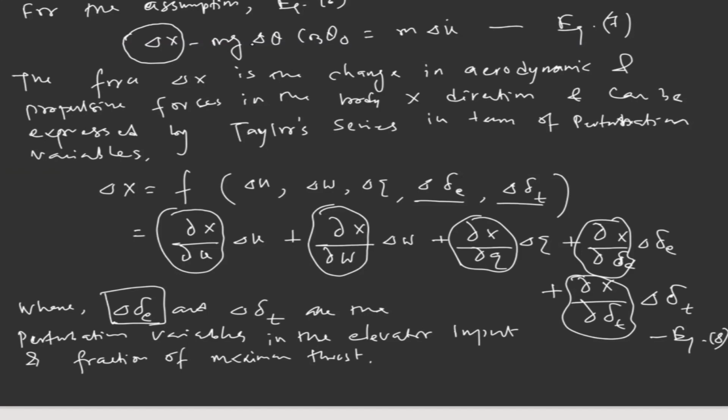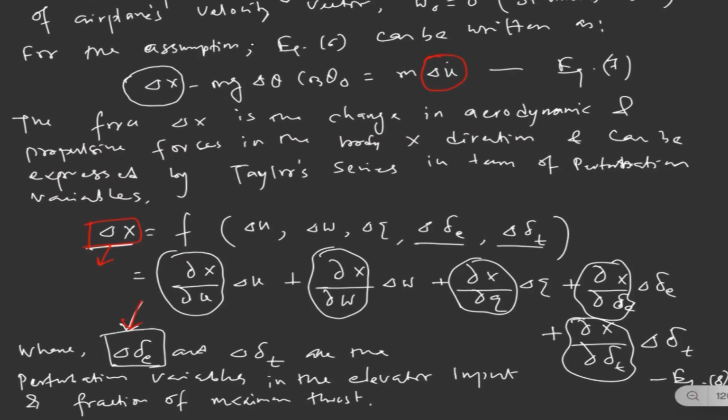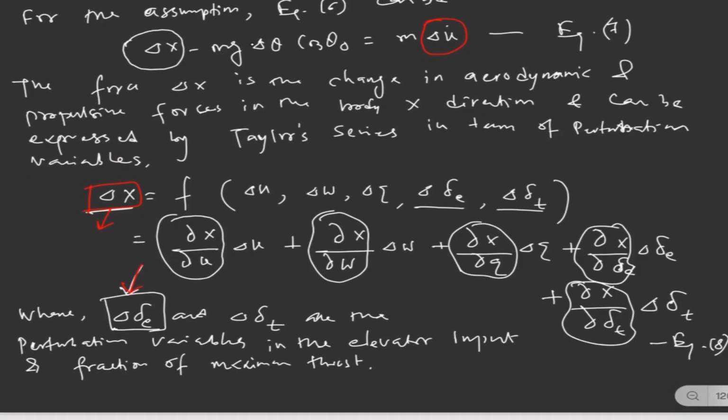And if it is going to control the delta x term, then we can say this is the favorable control input to the system, which can control delta x indirectly. Actually, we are controlling the delta u dot. So how can we make the time rate change of delta u equal to 0 with the application of this control input and the perturbation in maximum thrust?